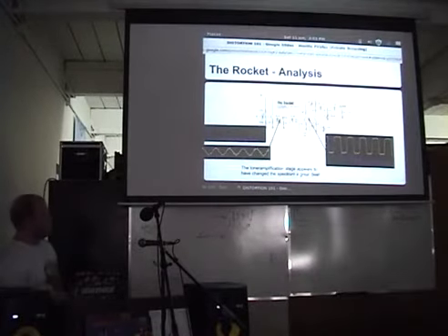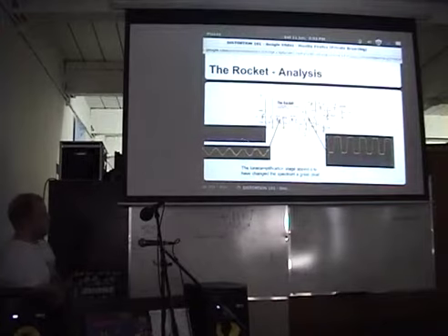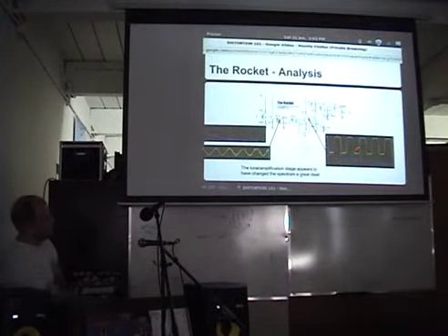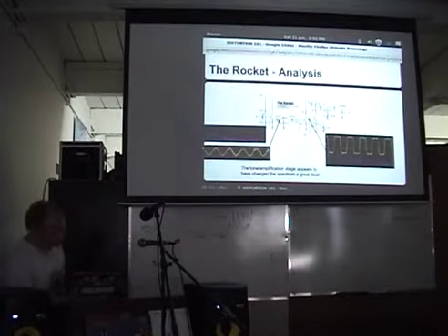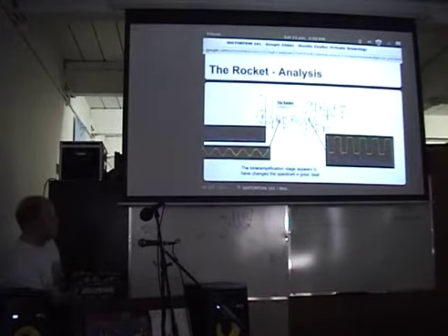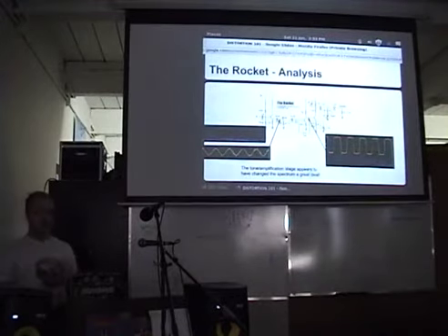So from a frequency perspective, you can see from this relatively pure tone to here, we're getting a lot of harmonics. It's a bit hard to make out, but the spaces between the peaks, I think, are about 5 kilohertz, which is the frequency of the fundamental.